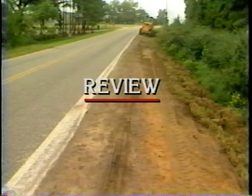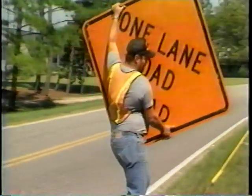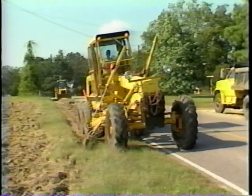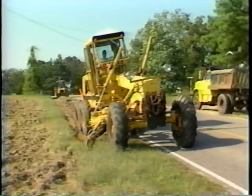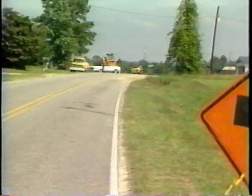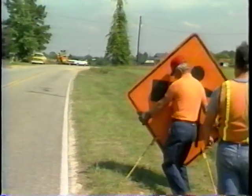Let us review the steps required for the repair of high shoulders. Number 1, place proper traffic control. Number 2, cut away high spots on shoulders. Number 3, pick up excess material and dispose of it properly. Number 4, remove traffic control.